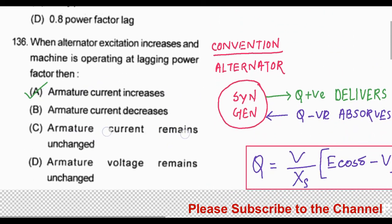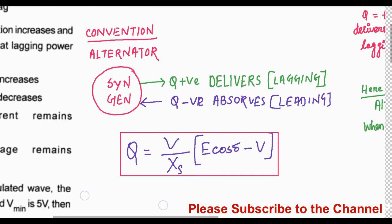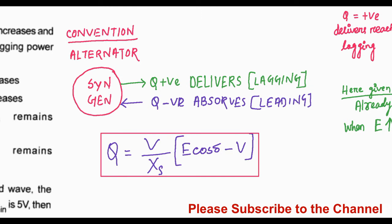Next one is, when alternator excitation increases and machine is operating at lagging power factor, then option A, armature current will increase, armature current will decrease, armature current remains unchanged, armature voltage remains unchanged. So our convention for an alternator is, as it is a generator and a source, if it delivers power then this is positive, and lagging is for reactive power delivery, and negative for absorption.